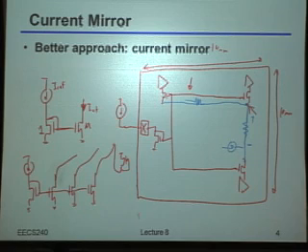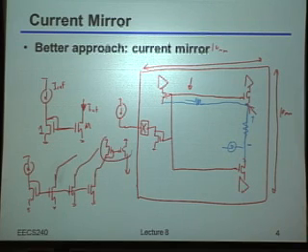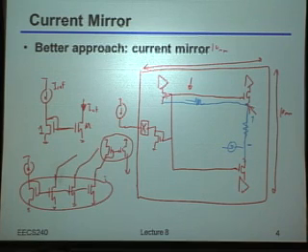Well, okay, let me draw that a little bit better so that it doesn't look funny. Right, once it finally gets to wherever it's supposed to go, you build the diode-connected device and you mirror it to flow into the circuit you care about. Okay? And again, the big difference here is that now these two transistors, and hopefully all of these transistors everywhere you do the mirror, should be close enough together, and you do a good enough job with the grounds in between them, that you really do believe that the ground or the VDD or really whatever the reference potential is fixed wherever you're doing that mirroring.